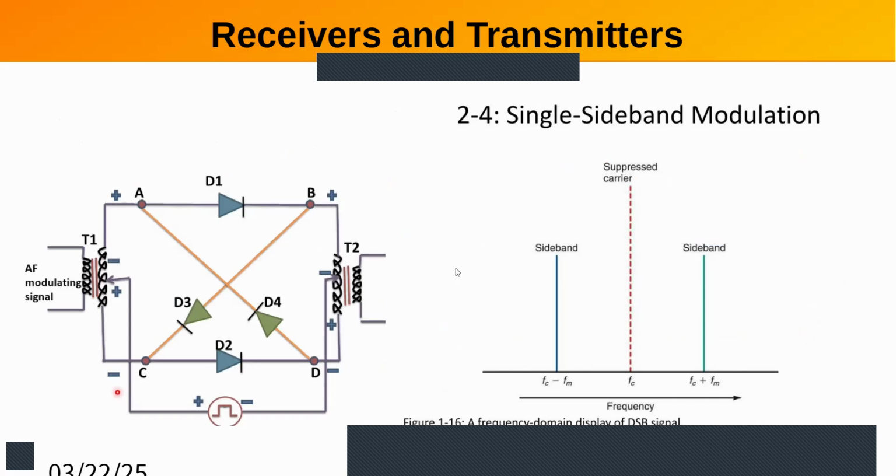Anyway, what you get out is these two sidebands, and this carrier should be suppressed, you essentially get nothing or almost nothing. You might still have what they sometimes call vestigial carrier, and sometimes they leave that in. I think in the old TV world, if I recall.